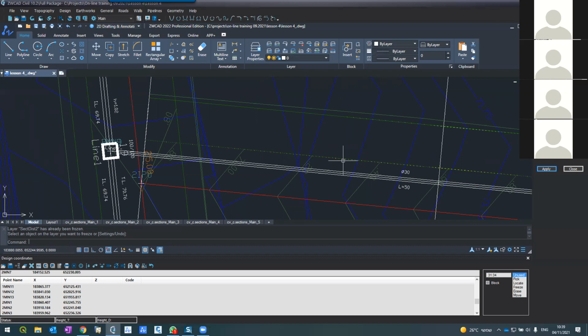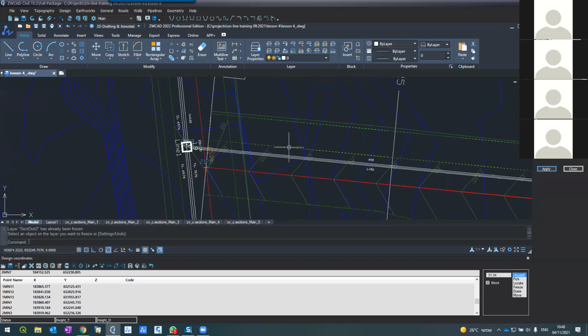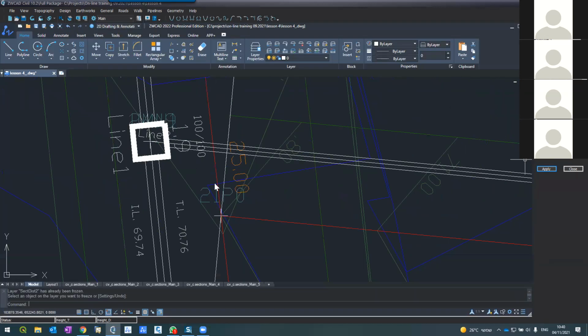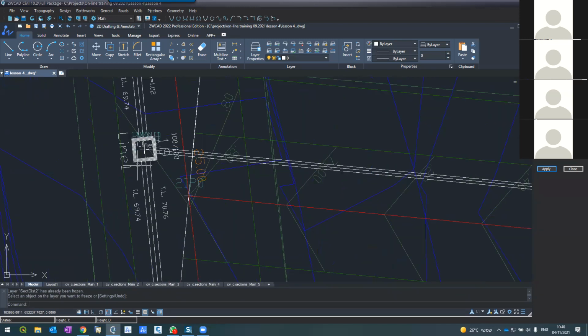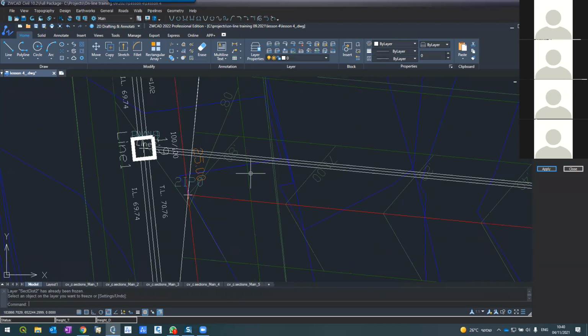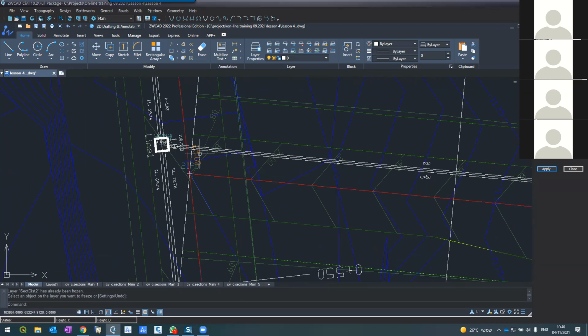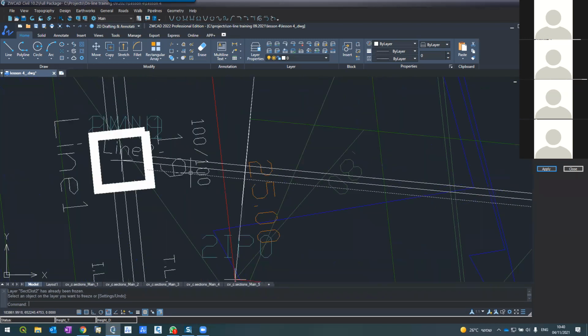There's another question. Since the unit of system is in meter, why are we using cm? No, the system unit is meter, but the good thing about pipes is that we can use different units for the length and for diameter. Of course, I can put it 0.5, but it's less popular, and the same goes for manholes. Manholes and pipes, usually we show it in more accurate centimeter.